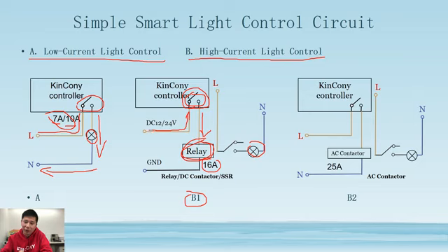You just add an external power supply of 12 volt or 24 volt, with a current of maybe some hundreds of milliampere. It's very small, and this protects the controller's relay and extends its life, because it is no longer controlling the lamp directly. If the external relay is broken or bad, you just replace it, and the circuit will have a new life.